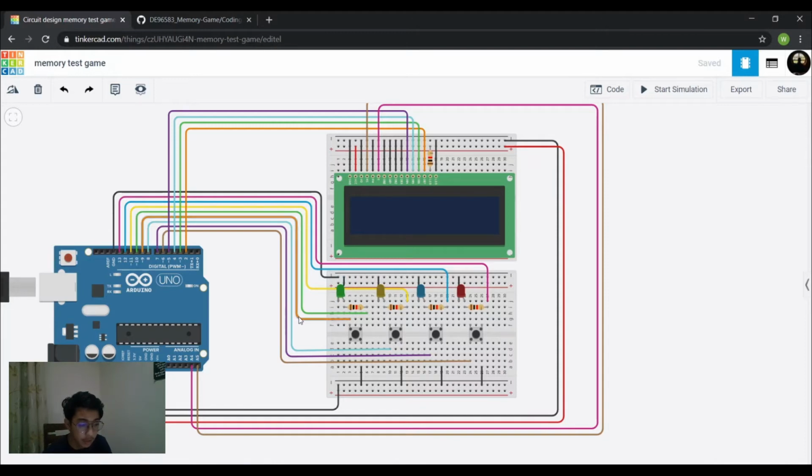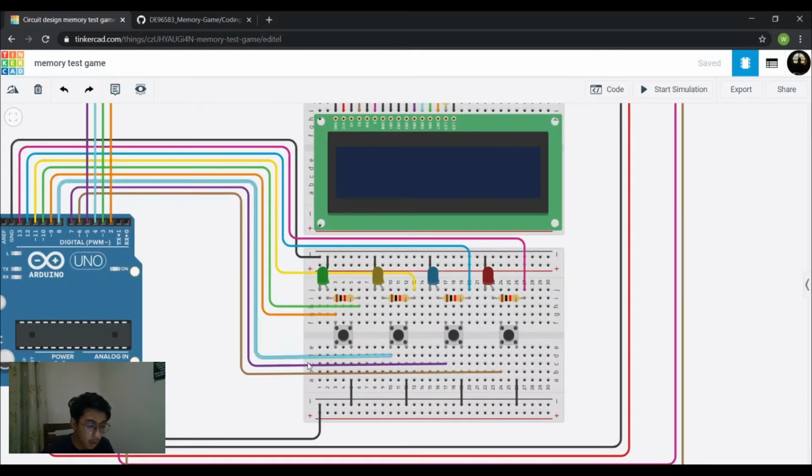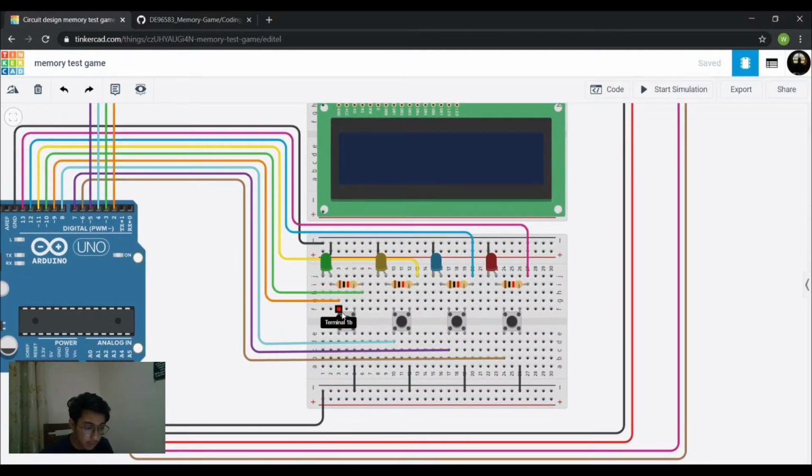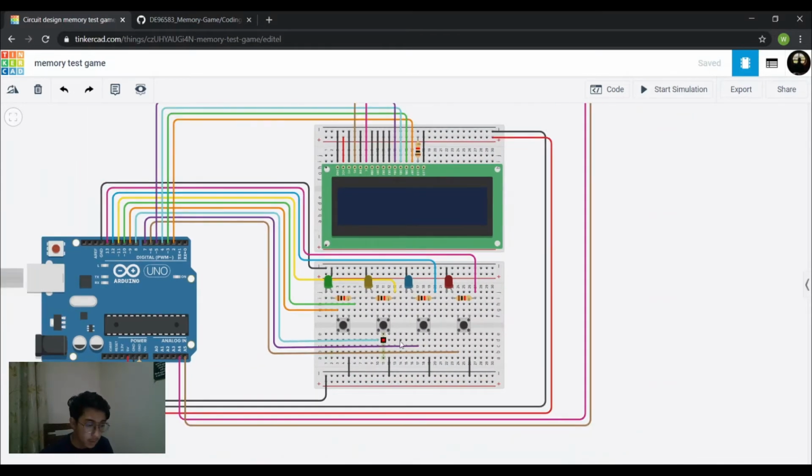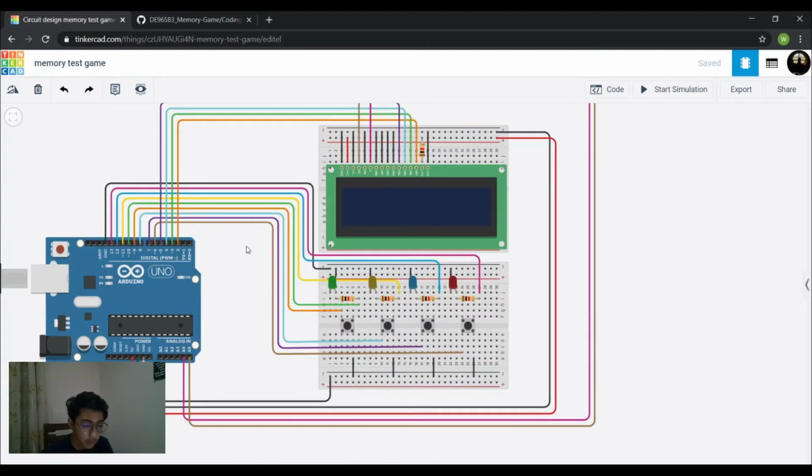The orange is connected to the buttons. As you can see, for the button, I've already connected on the top left side, then I've connected from the bottom of the left side. For the push button, the pins are connected on the left and also the right. The left is actually connected together, you can see terminal 1A and terminal 1B. Then when we push the button, this left side will be connected to the right side, which is terminal 2A and 2B.